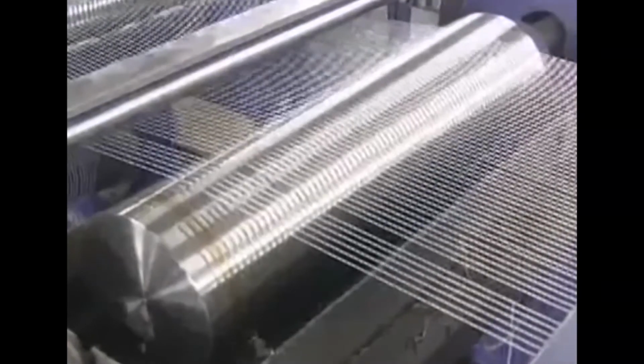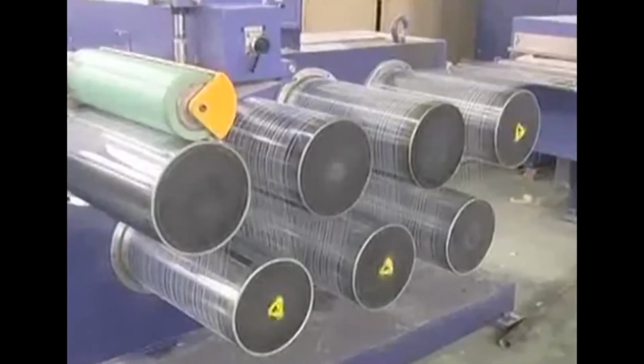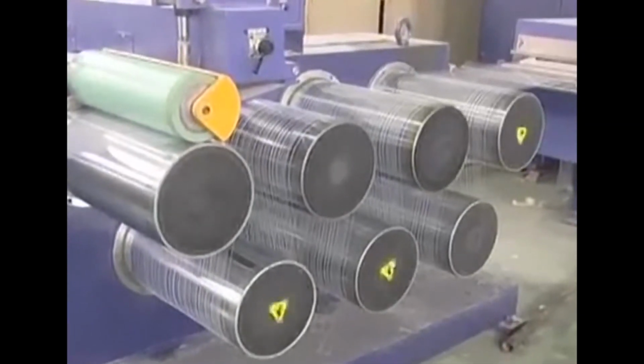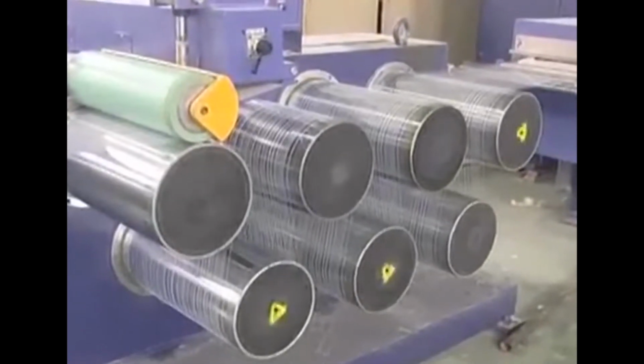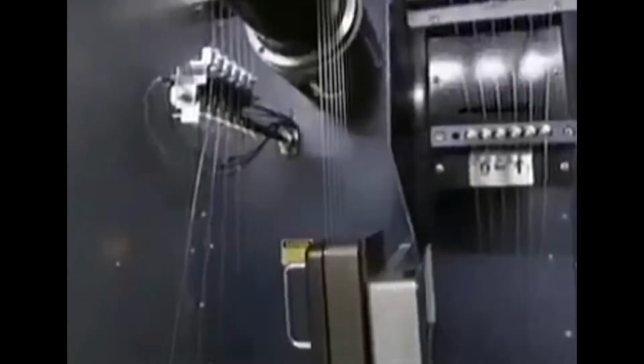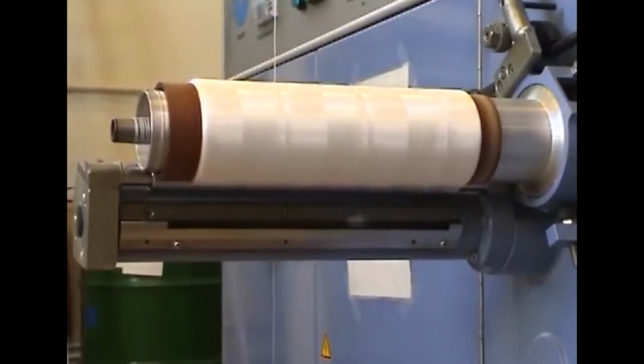So, when the filament is fed through it, the second one will pull it 4 times more than its length, and thus it attenuates the filament and also aligns the molecular chains to the fiber axis. The filament that comes out is wound on bobbins or whichever package they want, and then taken off from the melt spinning.